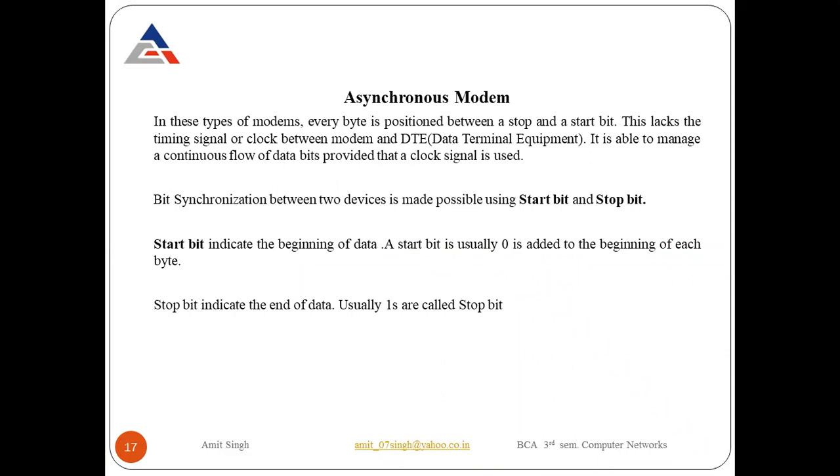Now the new concept in the case of asynchronous is this. Suppose I am the sender. Whenever I send any data, I use a start bit at the start and a stop bit whenever the data is complete. With the help of start and stop bits, the receiver can know when data starts and when it is complete. Whenever a start bit is there, that stream of data starts. Whenever a stop bit is there, the data is completed. That can happen in the case of an asynchronous modem.